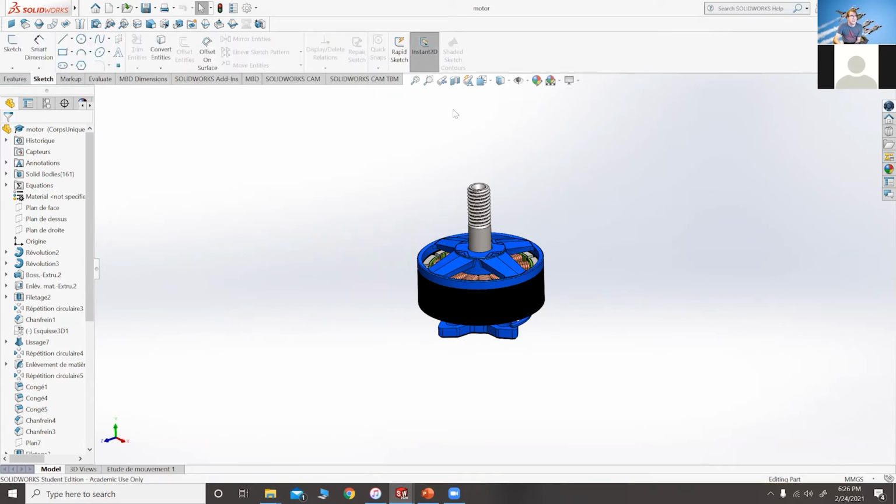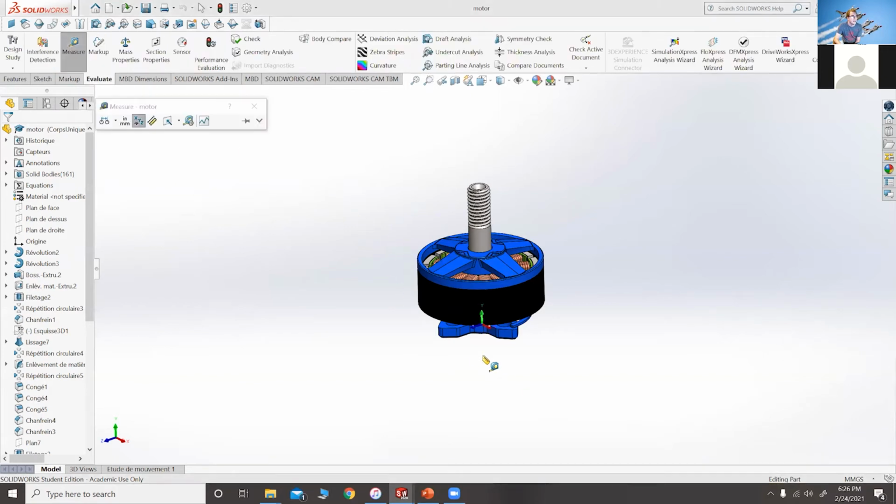Sketch pertains to when we're dealing with a sketch on a 2D surface. These are drawing lines, drawing circles, drawing curves, dimensioning. And the rest of this is sort of external to what we're focusing on today, but there's also some simulation things. Evaluate, we can measure things on the evaluate tab.